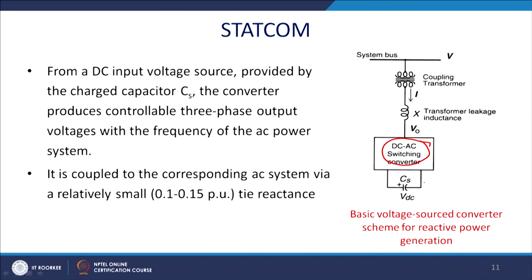Now, what is STATCOM? The principal operation will be the same, but here you will have DC to AC switching, and also AC to DC switching; we will have both. Generally it will be in this direction. These devices will act as a converter. It will convert DC energy to AC voltage, and in the other direction it will generate DC. So bidirectional energy will be propagating here, and the current should be bidirectional, and that is one of the features of the voltage source converter.